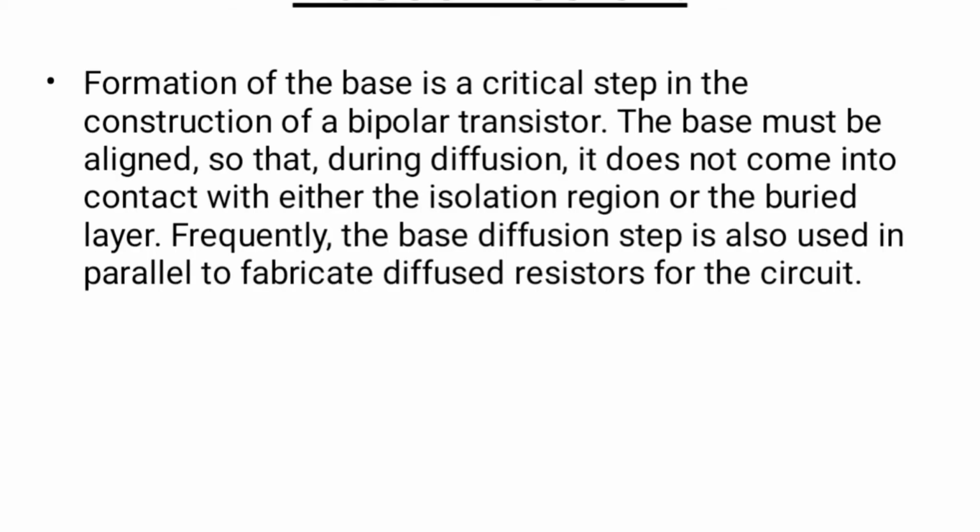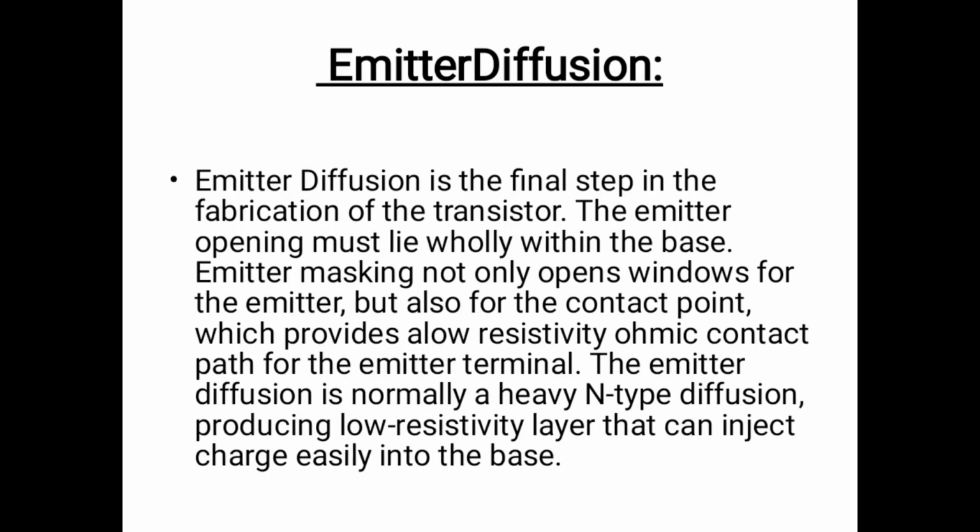Base diffusion. Formation of the base is a critical step in the construction of a bipolar transistor. The base must be aligned so that during diffusion it does not come into contact with either the isolation region or the buried layer. Frequently, the base diffusion step is also used in parallel to fabricate diffused resistors for the circuits.